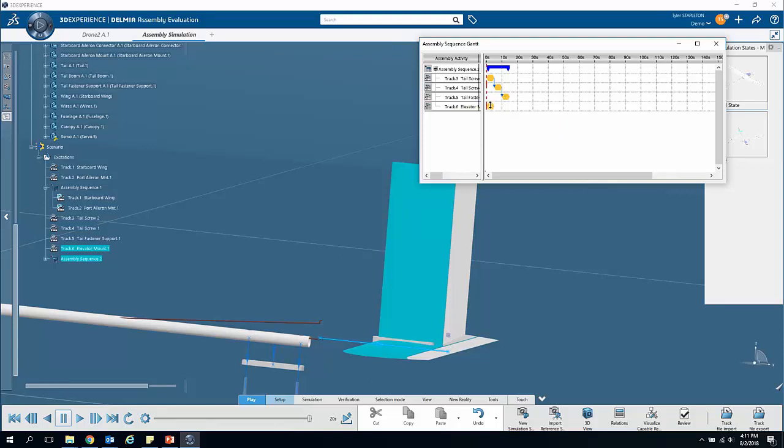The way to do that is you grab this little hexagon and look for that scroll up and down cursor. I'm going to drag that right on top of that hexagon before it. And that's going to create a parallel dependency. If I hold it after, it's going to recreate that dependency it had before, and I can drag it before to force that big tail assembly to come off first. I want them in parallel, so I'm just going to release there, and there's that parallel dependency.